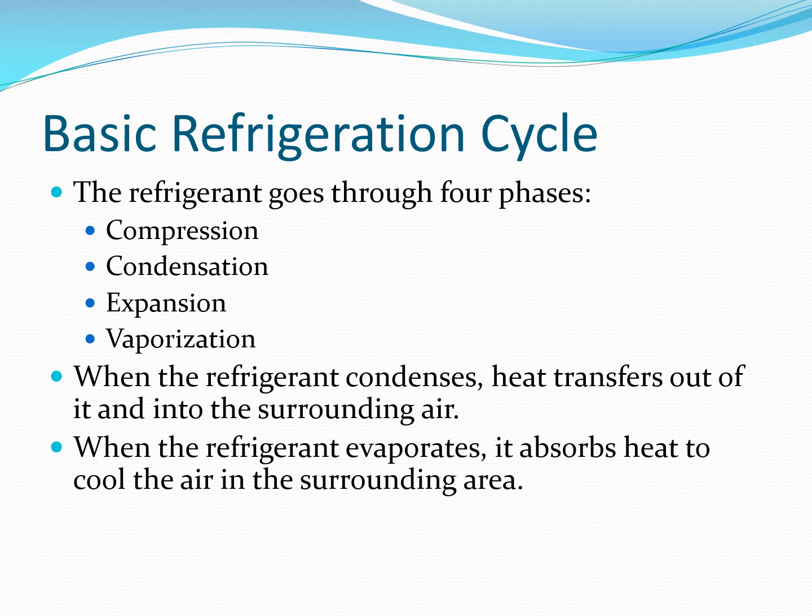Then you also have an evaporator. This is the part that's absorbing the heat from the surrounding area. So on a window unit air conditioner, that's the part that's on the inside of the house. That's the part that's on the inside of that window. And that's the part that is going to be taking the warm air from the room, running it over that evaporator, and then because that evaporator is cold, it's going to put out cold air into the room.